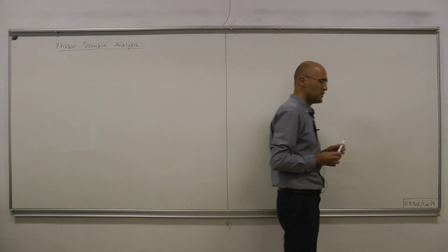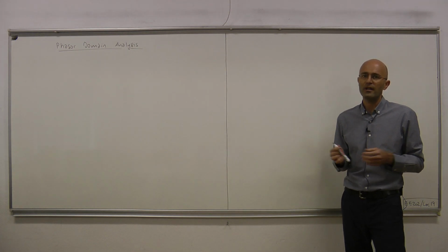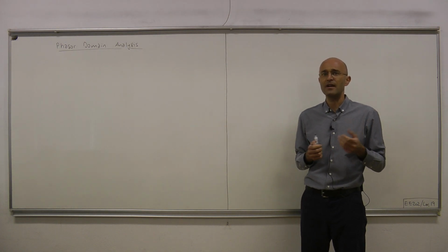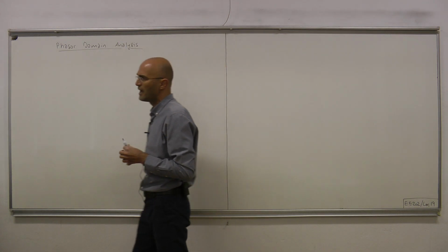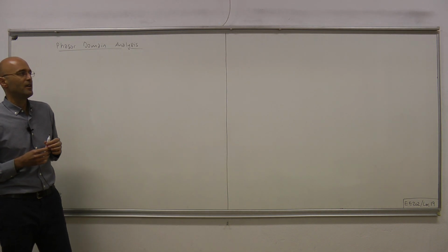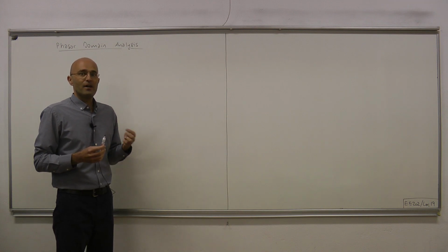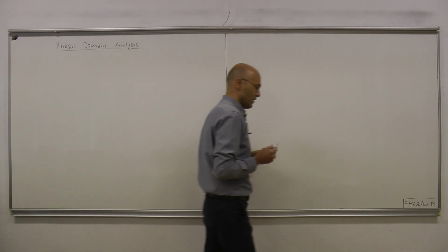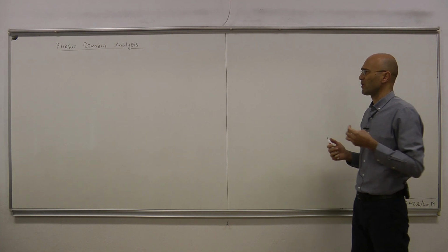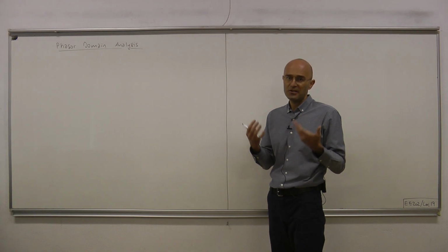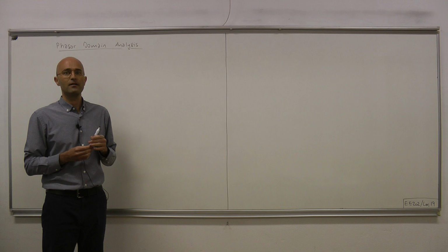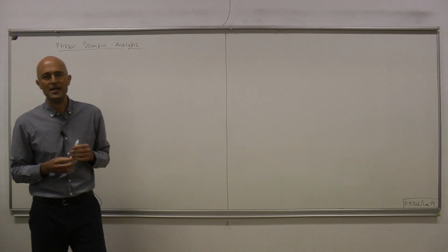This at first seemed like just a mathematical trick, but soon we discovered that it's more than a mathematical trick, it has some physical flavor to it, in the sense that the phasors satisfy KCL and KVL. Or to be more precise, the phasors of voltages satisfy KVL, we showed that, and also phasors of currents satisfy KCL.